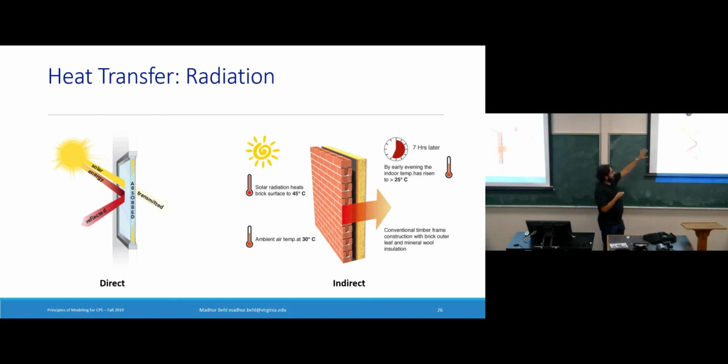So there's this fusion reactor in the sky, right, and it's constantly bombarding us with different kinds of radiation. Some of it is reflected back from, say, a glass surface. Some of this is absorbed by the surface itself, and then some is transmitted into the zone air. And so the cross-section area of the surface times some radiative constant of this glass will tell you how much of this energy flux on this glass surface is getting input as a heat flow into the zone, just using that simple equation.